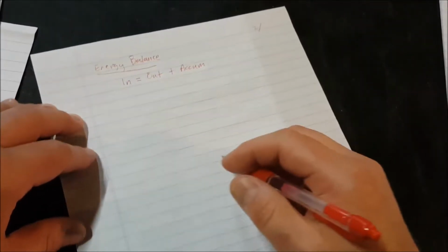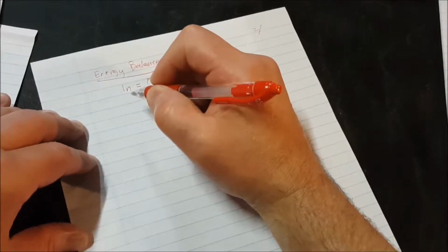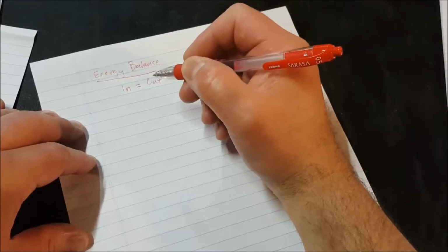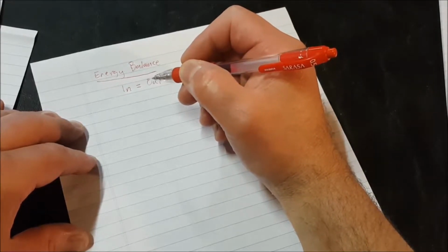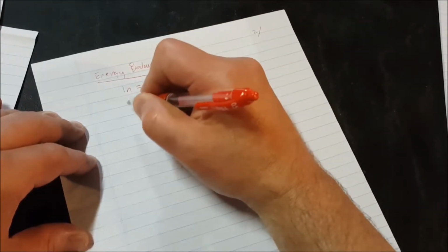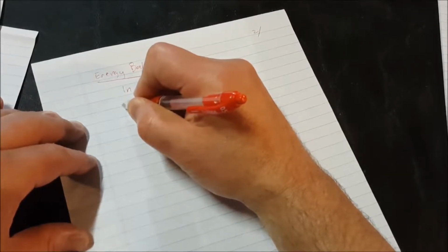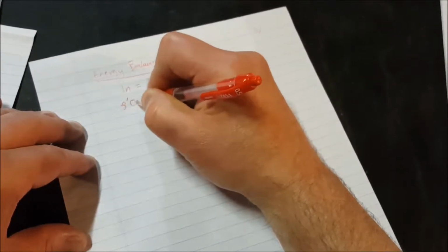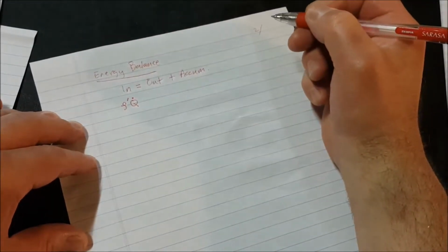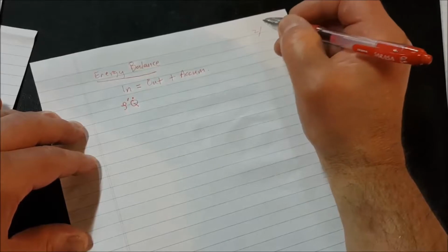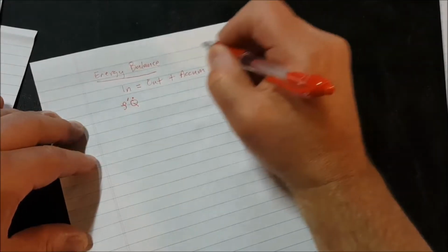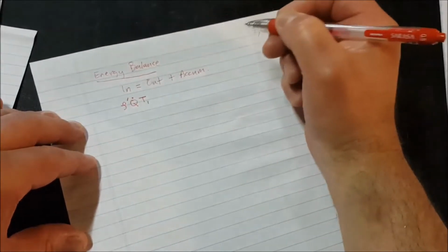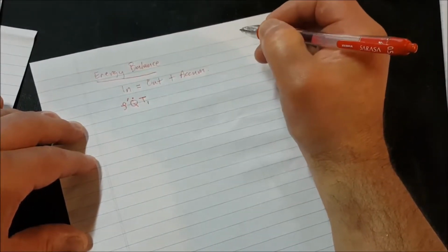All right, using the variables on page 1, then, in an energy balance for a stream, basically you want mass flow times heat capacity times temperature. Okay, well, I started out this problem talking about volumetric flows, so if you take the density times the volumetric flow, that's mass flow. So gallons per minute times pounds per gallon is pounds per minute. So that's mass. And then T1, because this is my return stream or stream 1.